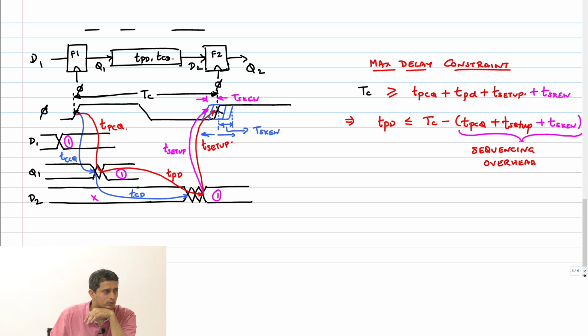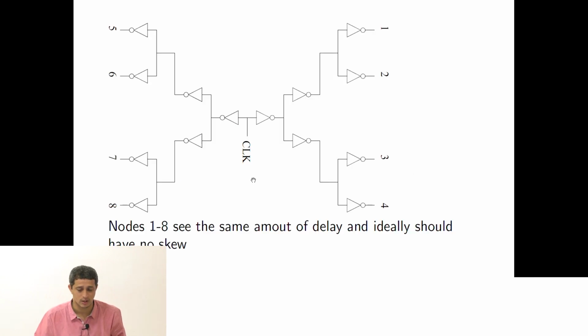D1 it arrives. So like I told you, the reference you have to make is with respect to one clock. My reference clock is not this clock. It's not with respect to this clock that the leaf nodes start deviating. This clock 1, the flop connected to node 1, will become my reference clock.